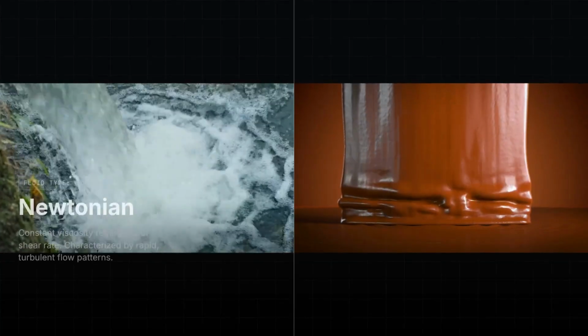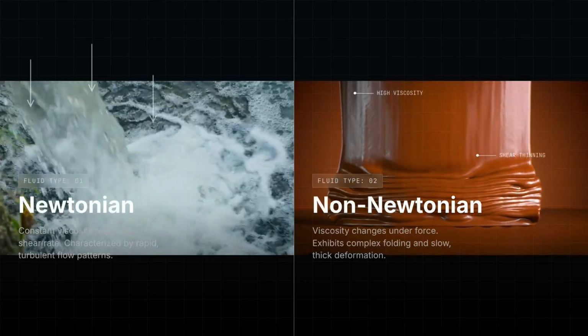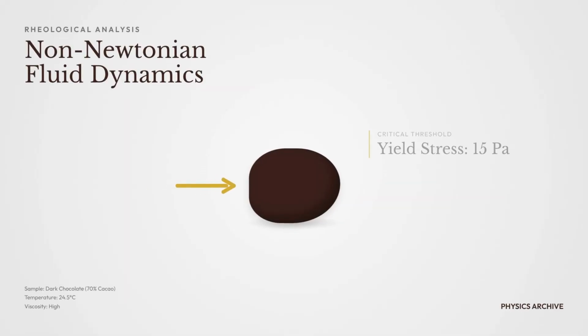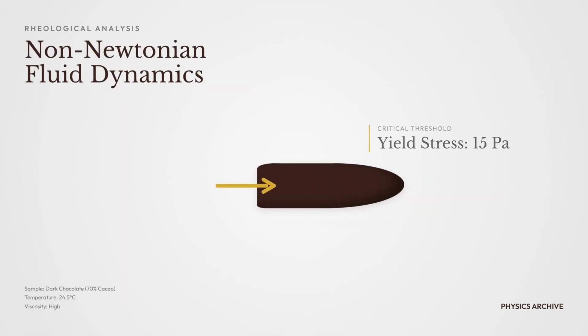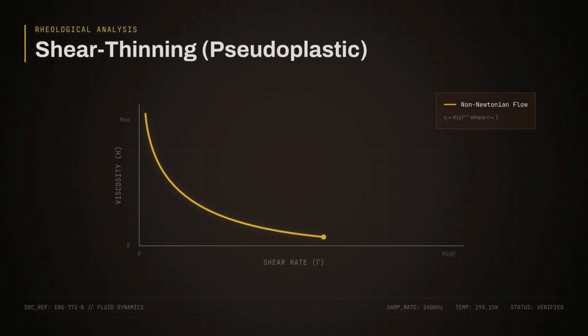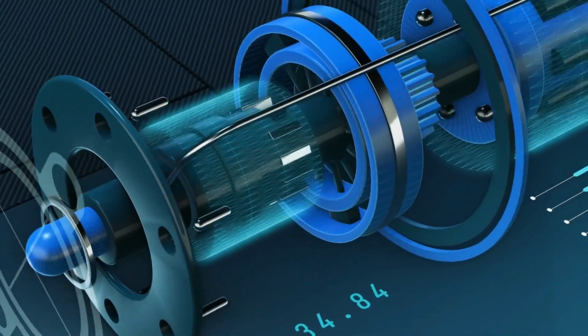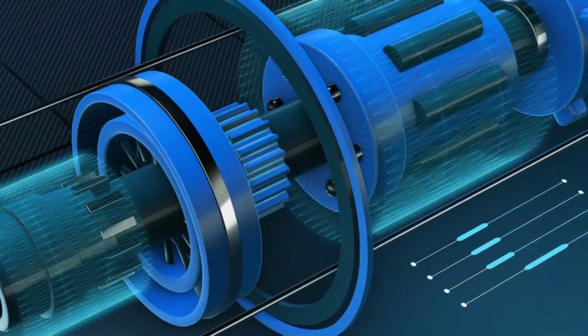Molten chocolate does not behave like water. It is a concentrated suspension of microscopic sugar and cocoa particles and fat. It has a yield stress, meaning that a minimum force must be applied before it begins to move. It is also shear thinning. As mixing or pumping speed increases, its apparent viscosity decreases. This is why conventional centrifugal pumps are often unsuitable.